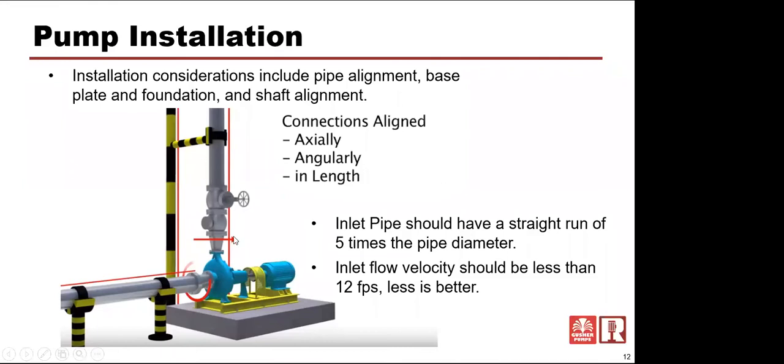Additionally, I walked into a plant where they were having problems with seals on a pump, and they had a set up something like this, but up at the top here, there was an elbow, and there was 700 foot of pipe connected going out to waste treatment. And all along that pipe, they had rollers supporting that pipe. So the pipe was supported vertically, but there was no support here. There was nothing to keep that whole pipe, 700 feet of it, from moving.